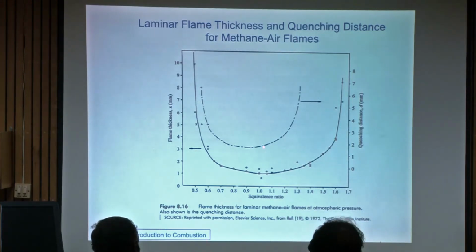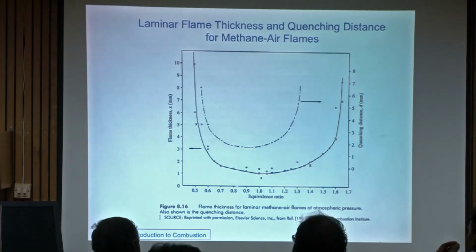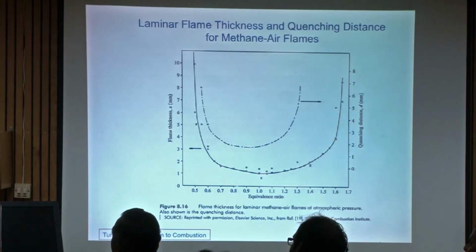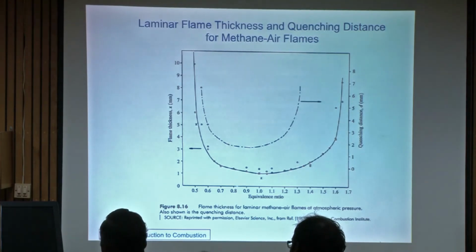I copied this directly from the book. Suppose you have a higher mass flow, so we can provide many tubes less than 2 mm. They don't use just the minimum tube diameter. They actually use the quenching distance to design what they call the flame arrestor, to arrest the flame, to quench the flame. They use something like a wire mesh.